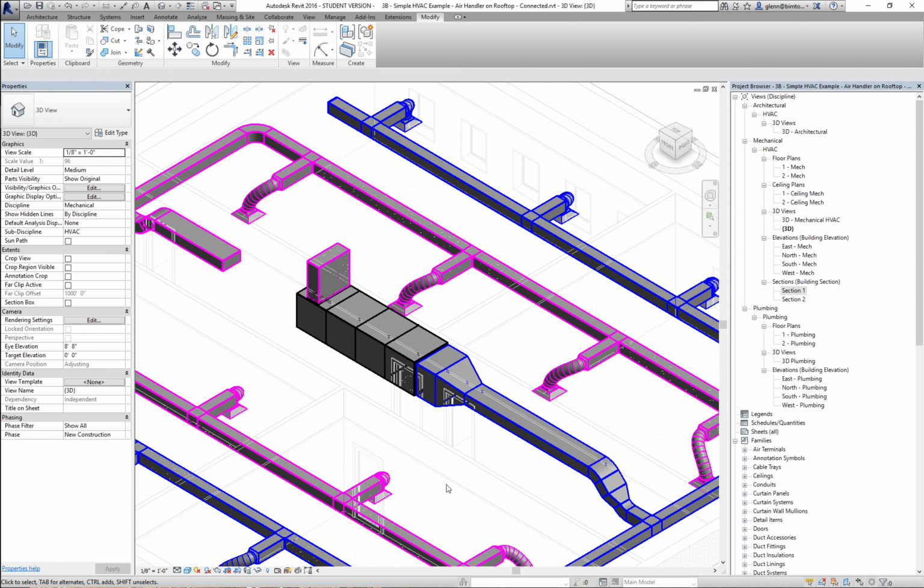What I generally recommend is see if you can get as close as possible to what you need, okay, and then do the final connection. So here's what my strategy is for this one. I'm thinking what I'm going to do is, over here, based on the one on the left-hand side, I'm going to pull that out a little further and up, like I'm sort of making the U for it, and even come on over, and then finally do that join with as little imposition as possible. If you can guide it as much as possible to tell it where you think the duct should be, it'll generally follow your guidance, and then you can let it figure out just the last few bits. Yeah, so it's a little bit harder to get all that stuff together. Let's see if we can make that work.